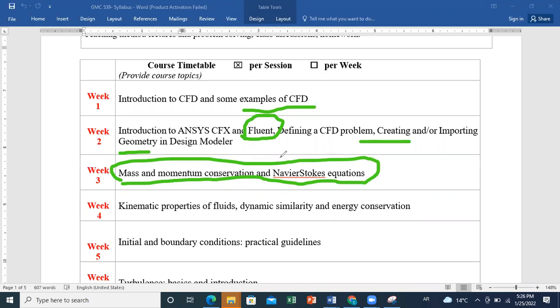So when you understand the physics well, if you have divergence, you can come up with several solutions to reach convergence. With practice also, you will have some expertise into what are the main reasons that can cause divergence. How can I reduce them? For example, I can reduce the mesh size. If I have a transient application, I can reduce the time step, etc.